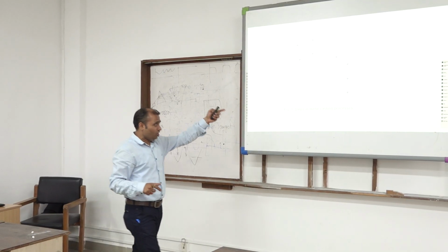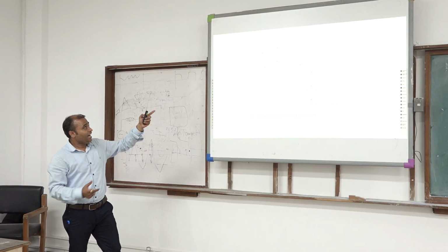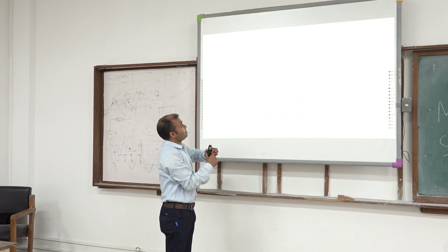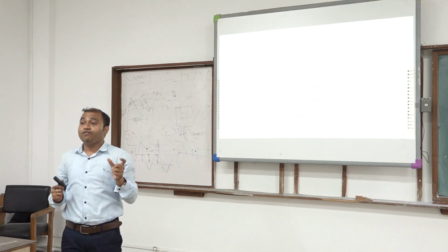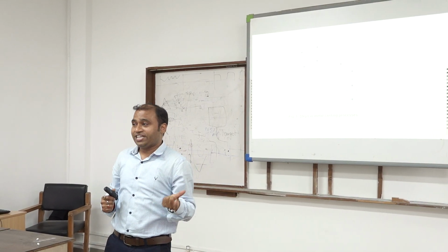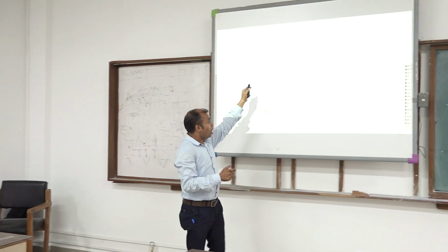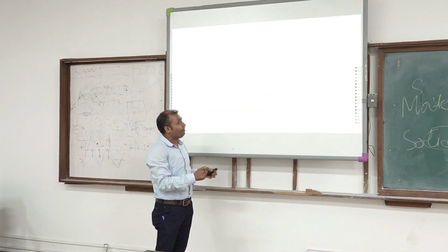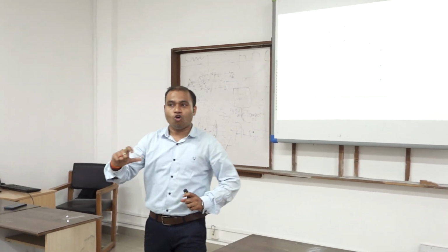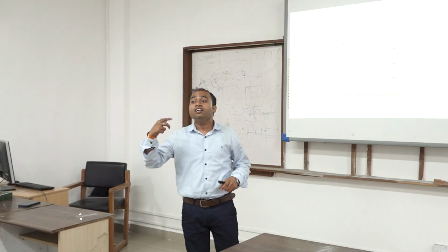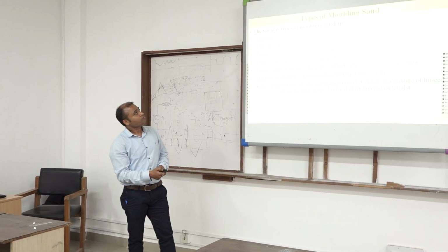So this only I have explained through the flow chart. Here I have taken the sand, that is the sand for sand casting. We will make the mold with the help of the sand in sand casting. Then we will pour the molten metal in the mold. Heat treatment is required if a certain strength has not been reached in the product. Then heat treatment is done, and finally the inspection is done.